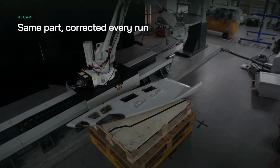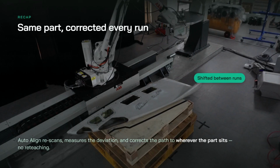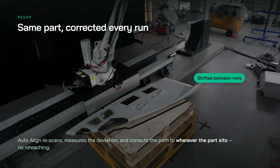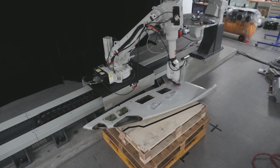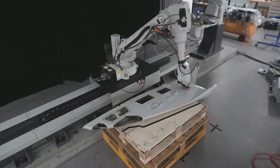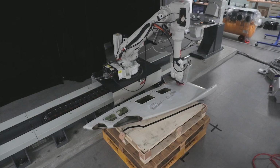The same part, in 2 different positions between runs. AutoAlign rescans, measures how far it moved and corrects the path to follow it. No reteaching. With the path corrected, the robot runs the process on the part, following the adjusted toolpath exactly where the workpiece now sits.